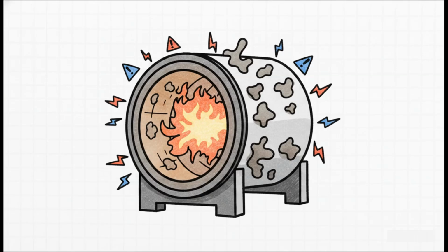Alternative fuels often have varying moisture content, totally different particle sizes, and fluctuating calorific values. If you let excessive AFR usage go unchecked, operators are going to face some gritty operational nightmares. We're talking unstable heat input, dangerous flame instability, highly variable burning zone temperatures, and just a massive increase in cyclone buildup and coating formation inside the kiln. The maintenance requirements can literally skyrocket.